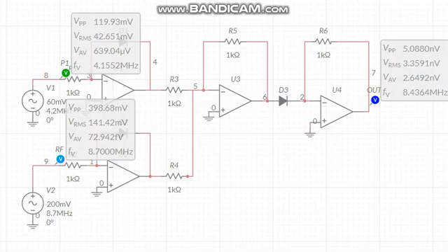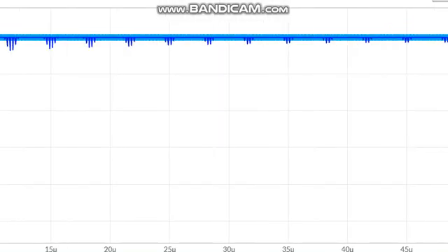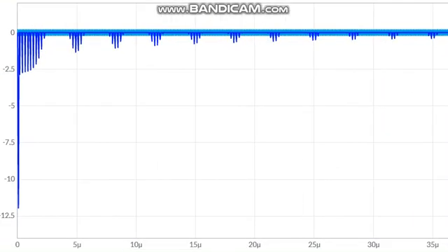If you want to understand the difference voltage, just think about the average voltage part. If you take the average voltage part, you will see there is a difference between these two. The peak to peak voltage is very small, in the nanovolt range, while the others are in the millivolt range. That means the difference is very small, and all the resistors are taken as 1 kilo ohm. So we just have to go to the graph section to see how that sequence really works.